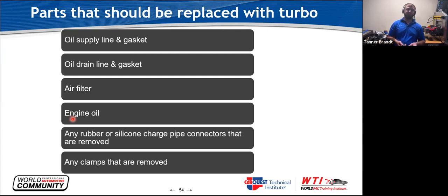They were aftermarket silicone pipes. Those clamps, as you take them on and off, will crack. And I've had them crack before on vehicles after they leave. They're a spring type clamp, so you can't really over tighten them unless you really mash it on there and compress the spring, but you're supposed to tighten them down until it compresses the spring a little bit, and the spring continuously holds pressure as it stretches and moves, but they can crack.